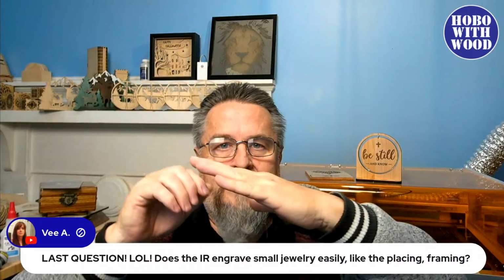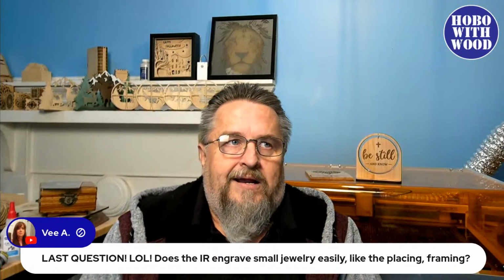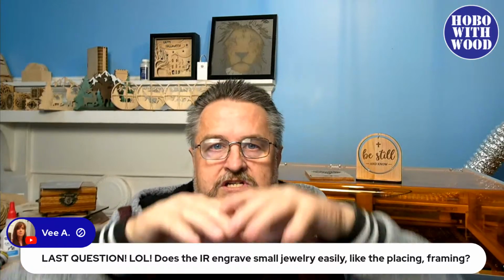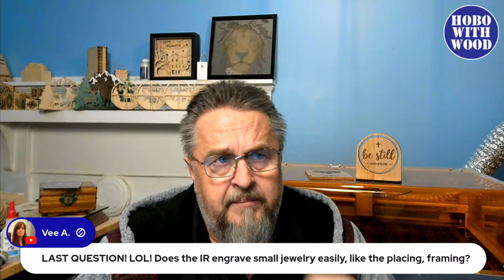But you can't have it at too sharp of an angle, so it distorts your letters and they look funky. It's tricky, but if you're doing just a top surface, yes, you can do that. And because it's only a 2.5 watt and it's going to be infrared, it's going to be a very small spot size. I can't remember what I read. It's going to be at least as small or smaller than a 10 watt diode. I'm pretty sure.